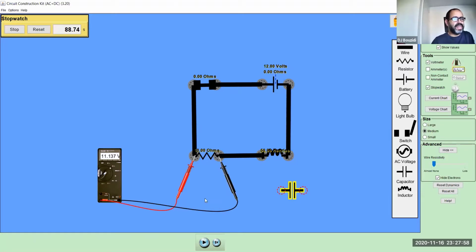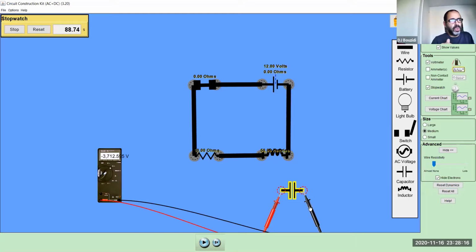But when you do that, try to bring this one to the ends in here. Don't connect it to the resistor, okay? For some reason, I have a voltage already across it, okay? Make sure when you bring it in there, then the voltage should be Q over C. And Q at the end, so the voltage at the end should be 12 volts, because C is 0.05, times the EMF, which is 12, and you divide it by C, 0.05, so the voltage at the end is 12 volts. So put it in across the capacitor and wait to see.